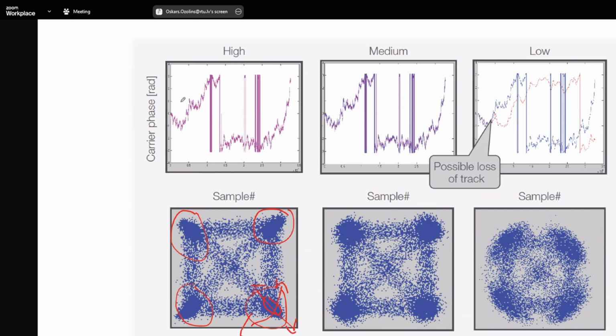And there are something like these cycle slips, where you just slip the phase to some other place. So if you can track the phase noise, then you can skip almost all the cycle slips. A cycle slip happens when your phase noise estimation just jumps up and down, or just continues there. And these cycle slips can also create an error there.